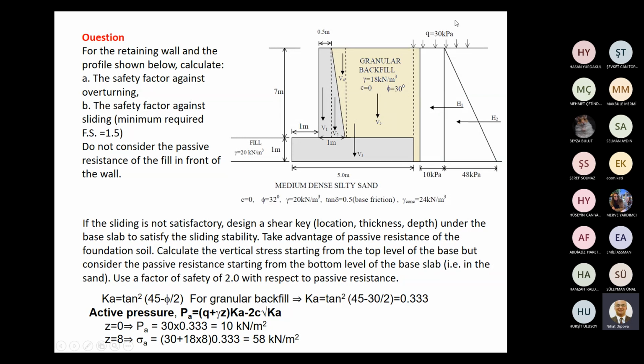Again, we have a surcharge value, and this surcharge value is the same along the depth, but the earth pressure will increase according to depth, and stress distribution will be triangular.